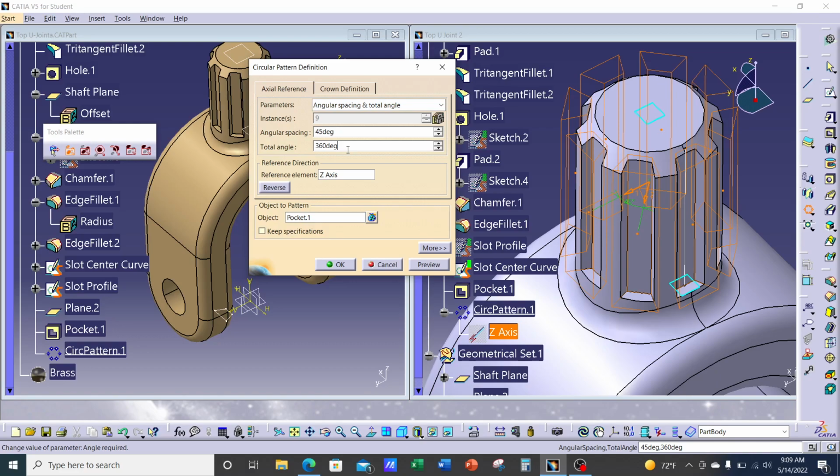I'm going to hit the backspace to remove the DEG, the degrees. Then I'm going to go minus 45. The reason I remove the DEG is because if I have 360 DEG, then I have to go minus 45 DEG. The units have to match. So I'm just going to remove the DEGs and let it do the math and insert the DEG on its own. Now I'm going to click away. Notice it does the math: 315, so 360 minus 45. And it automatically gives us 315 DEG, inserting the degrees.